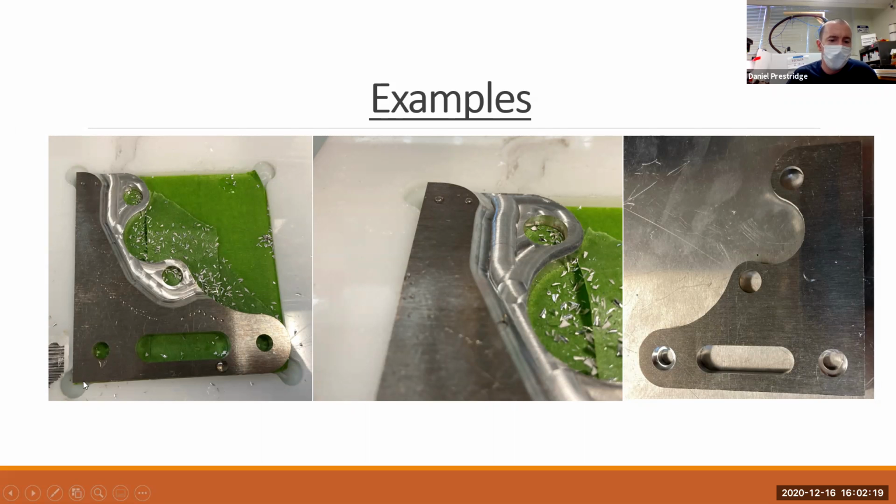So we did the same thing, cut this corner, did the holes, placed this, we still had the 0 here, did the front features, and then flipped it over and did the back features, which are these countersunk holes, which had to be exactly where they needed to be. So that was an adventure, and we're actually going to go back afterwards, after all of this, and I'm going to show you the cam that we made for it, so you can sort of see the process starting from a block to what we see here.